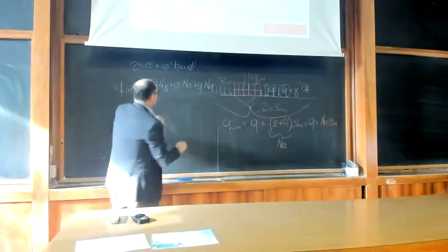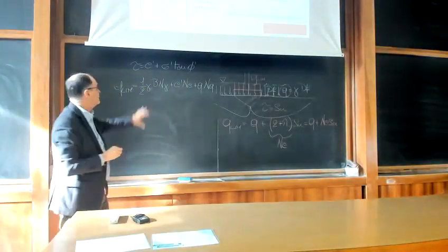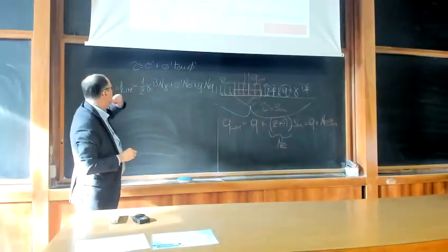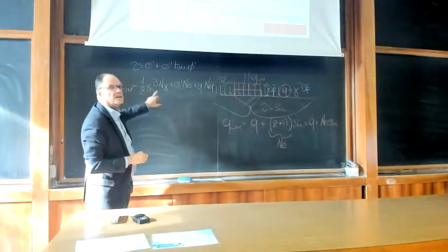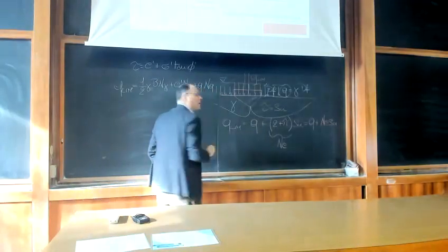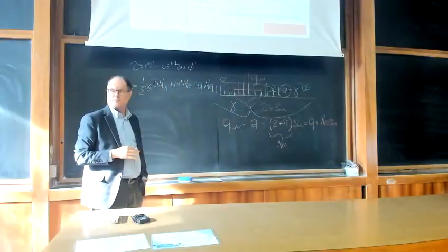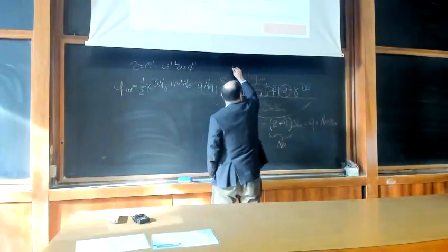So this should be written as C prime, because we are following this criterion. Gamma is the weight of the soil below your foundation. B is our footing breadth.